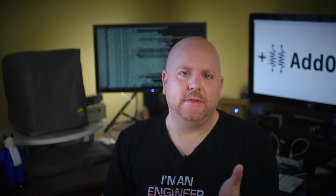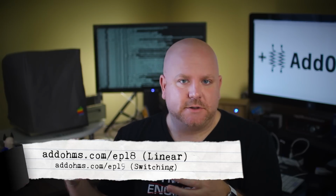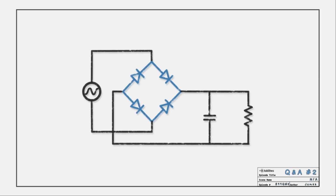And so basically what you're doing is you're taking the wall voltage, converting it into DC, and then using regulators, like we talked about in number 18 and 19, to get the DC voltages. So that's what's going on there. And that's definitely something I want to cover more in the future with a diode bridge or rectifier bridge and transformers, and that's actually a cool circuit to take a look at.